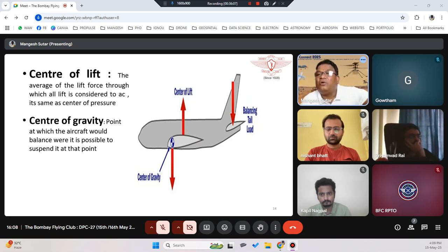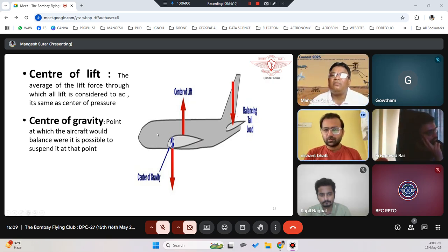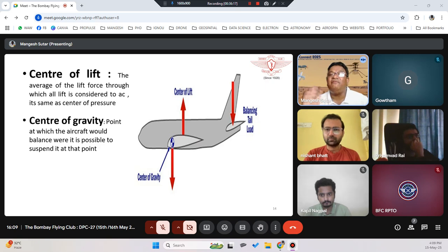But then what about the case of rear-engined aircraft? See, the engine is only giving thrust. It is not adding any lift. Wherever you place the engine, it is only generating thrust, a forward motion. Your lift is being created by the pressure difference, the Bernoulli principle. Just putting an engine will not make it fly. For example, if I attach an engine to a car, will my car fly? Because there is no aerodynamic surface, it will not fly. It will just move forward.